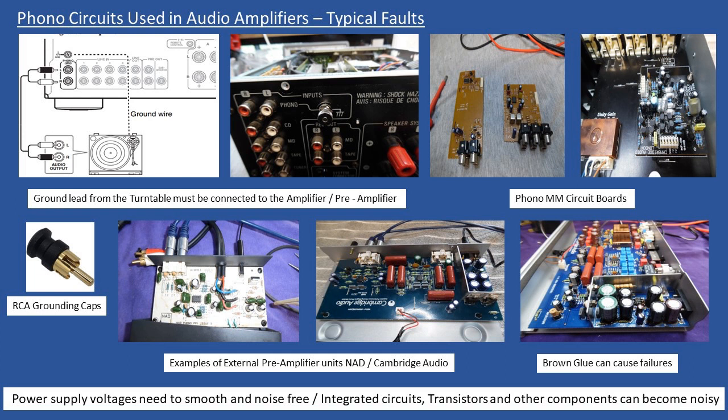So when I think about ceramic disc filter capacitors used for high frequency filtering, the dielectric inside again can start to break down, so you can hear this noise. Now if you use maybe an oscilloscope and you're trying to fault find, you may see something, but for myself I always use an audio signal tracer, and that's very effective because the probe has a capacitor inside which blocks any DC, and then it goes into a small operational amplifier, and I can hear the audio, and I can literally put the probe and trace through the noise.